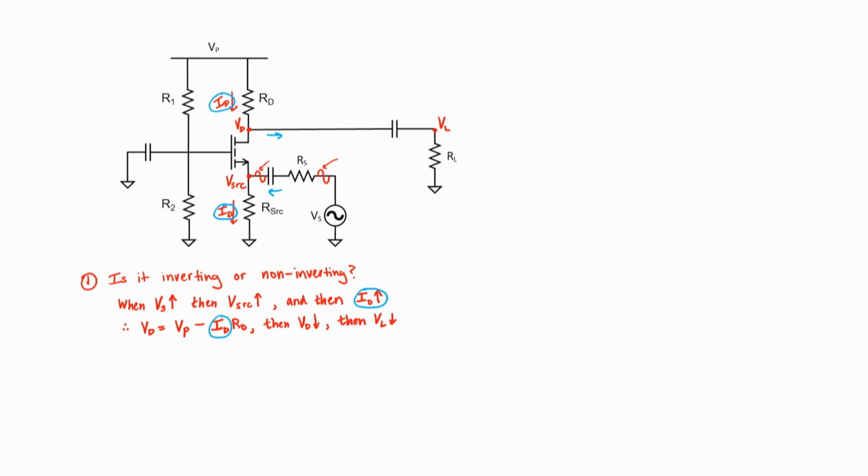Because we have an AC component that actually determines whether the configuration is inverting or non-inverting, those portions of the drain current actually matter here. Let's see how they matter. And so that we don't get confused, I'm going to just draw a line through the incorrect part of our derivation. Let's temporarily remove our markings for the drain current from the circuit diagram.